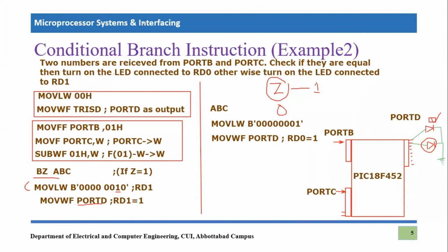So what we are going to do here, we will use the unconditional branch, which is BRA, and we will move it to XYZ, and let's put XYZ over here. Then we can simply terminate our code with the assembler directive.